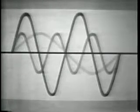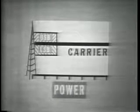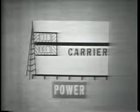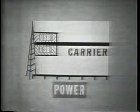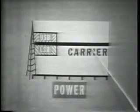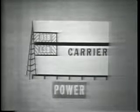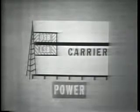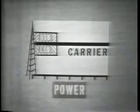Let's look at it in a little different way. We'll begin to see some undesirable things about the conventional AM signal. After the sidebands are generated, the carrier is not required for transmission of the sidebands. Now, since the carrier is constant in amplitude and in frequency, it contains absolutely no information at all. So why transmit it? Yet 2/3 of the total power is wasted in transmitting the carrier. Thus, the sidebands are being deprived of power which might increase the range of transmission.